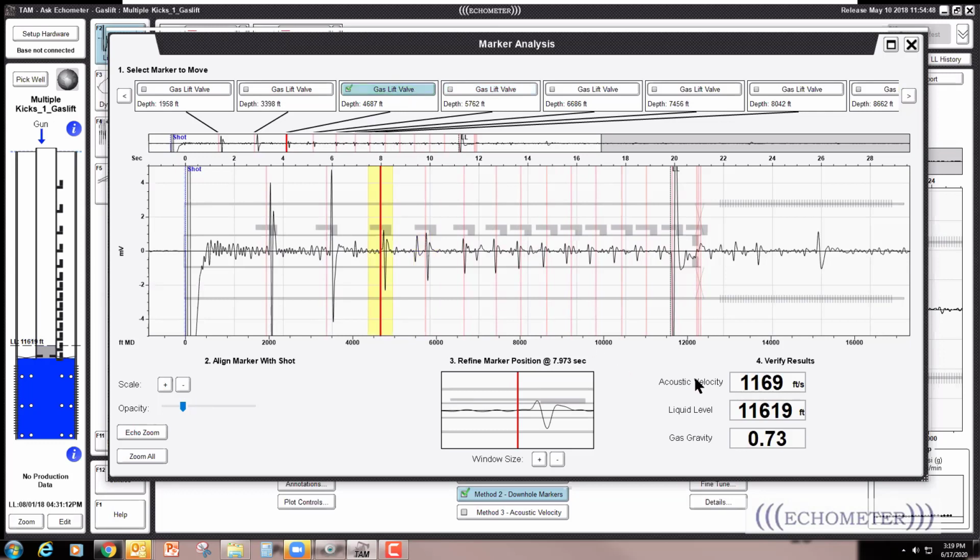See here we've got a reflection, so if you're working your way down, Carrie Ann, show over on the side that the gun's attached to the tubing. Okay, here. And the kicks are up, not down. So you tell the software whether you're shooting down the tubing or the casing. Here we see this as a shot down the tubing, so we see the gun with the arrow on the tubing side. And as Lynn mentioned, these are up kicks, so we're shooting down the tubing.